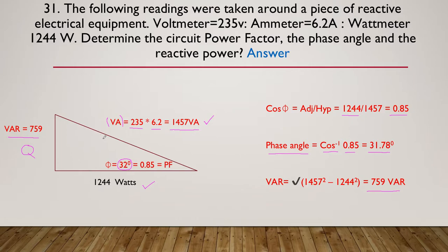And again, can we check our answers? By doing the phasor diagram, we can see that the watts is a fair bit less than the VA. That makes sense. So by comparing those two, we can say to ourselves, yeah, tick, probably right. And we look at the Q, and the Q has to be less than the VA.